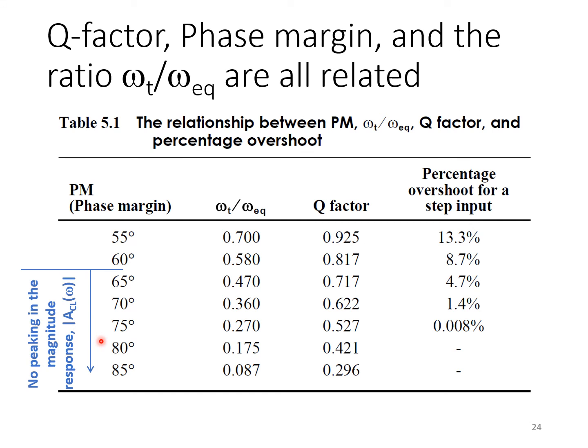And then in that case, you may target by design a phase margin of 85 degrees, let's say, just to provide you that extra 5 degrees safety margin in the presence of process, voltage, or temperature variations. But in fact, the 80 degrees is a hard spec. It's not just 80 degrees of safety margin to stability. The other noteworthy fact that you could see from this table here is that in order to ensure, for example, no overshoot,